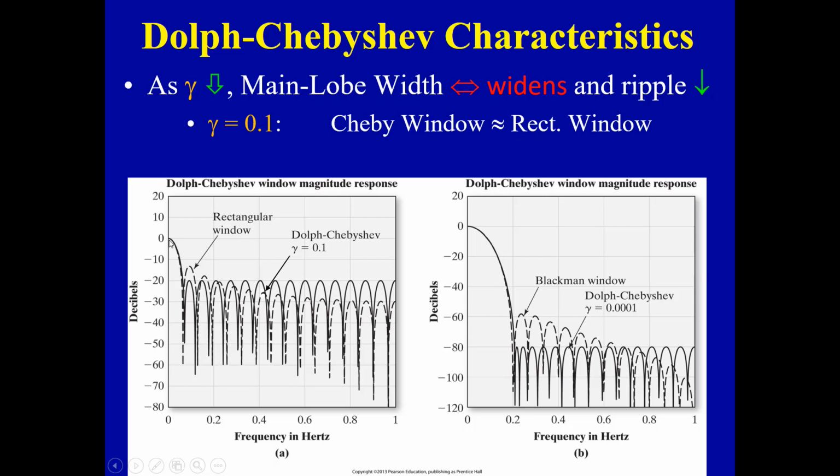Notice that for the same main lobe width as a rectangular window, the Dolph-Chebyshev does a little better in worst case attenuation and is flat, whereas the rectangular window rolls off a bit. So again, this is that optimization. The Dolph-Chebyshev window is trying to maintain the same value of attenuation at all frequencies for a given main lobe width. And actually, the other way around. I'm sorry, for this amount of attenuation, it's trying to give you the best you can, and give you then the best main lobe that you can achieve for that amount of attenuation.